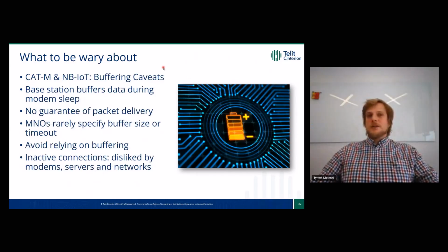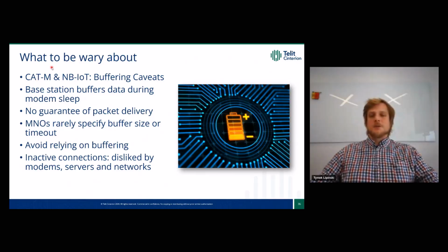Other caveats. What happens when we have CAT-M or NB-IoT, we are using eDRX or Suspend mode or PSM, and right at this moment, our server sends some data packet, 1 kilobyte, to our modem? Well, there is a buffering option on the base station itself. The network acknowledges those packets, and the network knows that the modem is currently in eDRX or PSM mode. So the network is unable to deliver this packet right now, and it will buffer it until the modem becomes available.